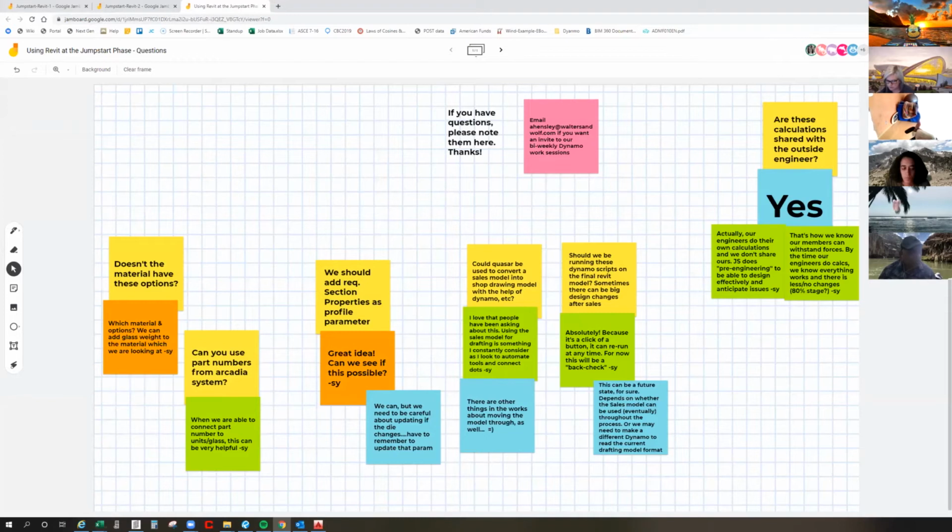It could definitely be baked into a process somewhere, probably Heather's die process where she gets the final die print, and an actual IXX, IYY published value can be put onto the portal where anyone can look it up under the engineering tab. But right now they're not stored anywhere, which is going to be one of the problems I'm going to have when I try and automate the vertical deflection calculations out of Revit. I don't have any of those section properties anywhere. So I either have to calculate them on the fly based on the die picture, or have them stored somewhere in some earlier process.